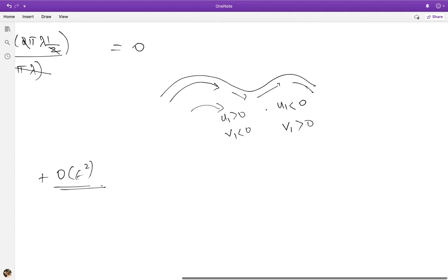The perturbed pressure gradients will also behave similarly. As the fluid converges, the pressure gradient in the x direction will be negative, allowing the fluid to accelerate, whereas the pressure gradient will be positive in the diverging regions, meaning the fluid goes into regions of higher pressure, causing it to decelerate.